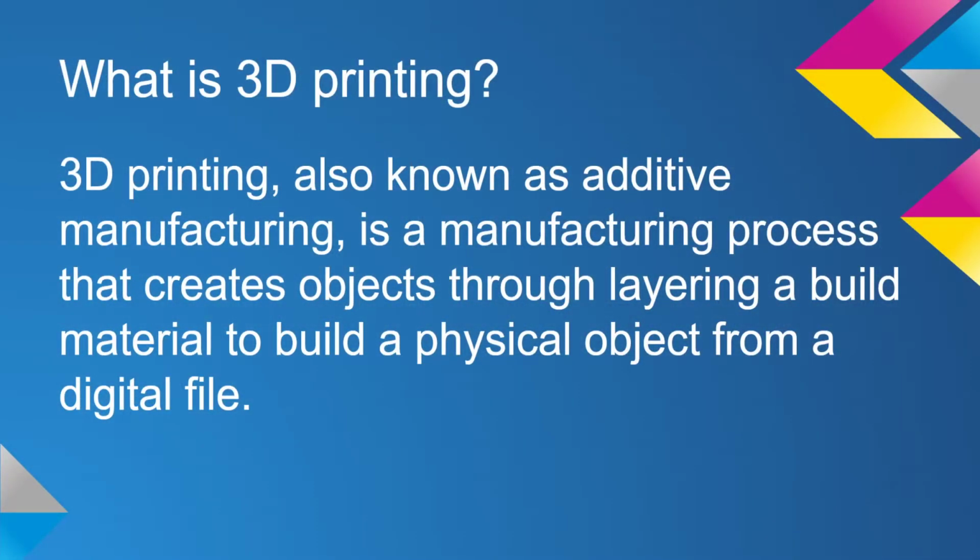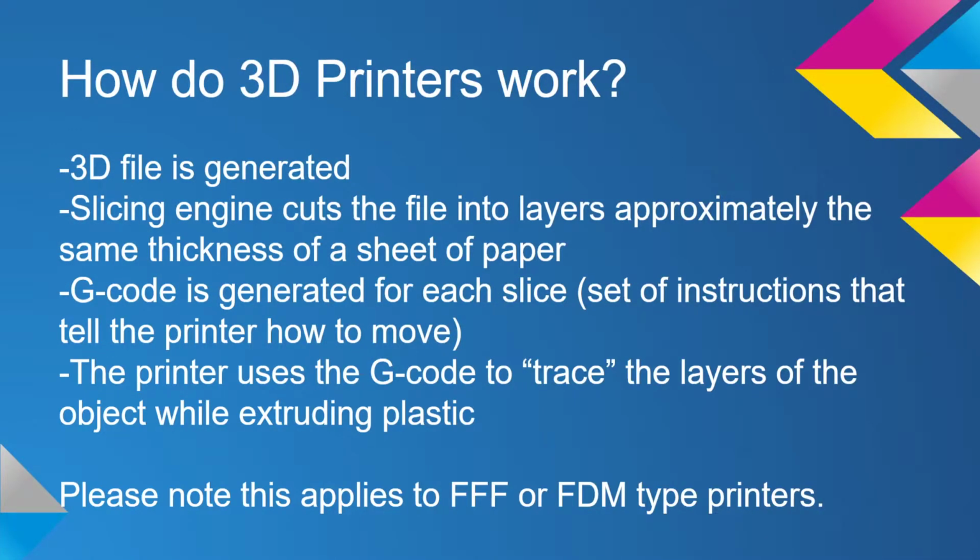So switching back here, that whole workflow starts with a 3D file. You have to have a design file for 3D printing. You have to start with something. So you take your 3D file that you either found or designed yourself and send it to a slicing engine in a slicer program. Based on the input you give it, it will slice that object into tiny layers, about the thickness of a sheet of paper.